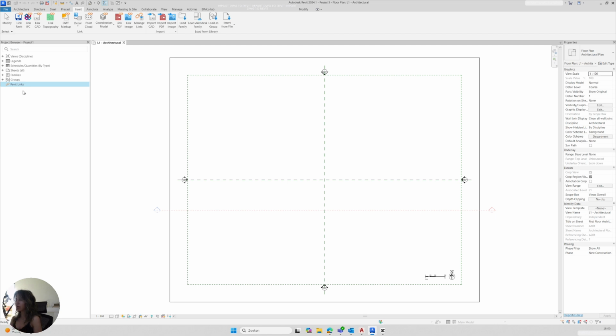It will be there, and whenever you choose, you can just make it disappear and then make it appear again. And whenever you change your original file, like AutoCAD file, and then you reload this here, you can see the changes will be made automatically. So you don't have to import your file over and over again each time you make some changes.